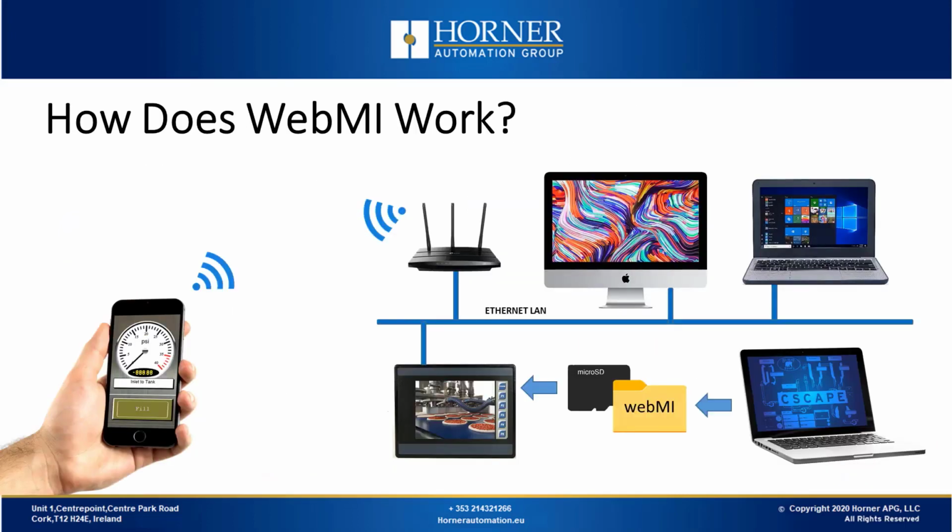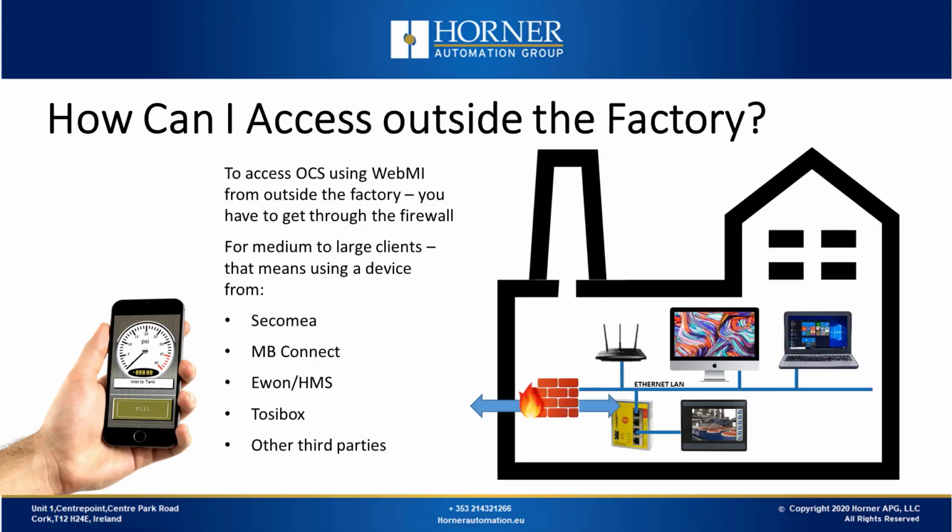So how does WebMI work? WebMI web pages are developed in Cscape. They're loaded to a folder on the micro SD card that has to be installed in the OCS prior. And if that OCS is connected to a local network through a wired or wireless connection, it can then connect with other devices through their own web browsers. It is important to add that wireless connections bring the possibility of mobile WebMI connections.